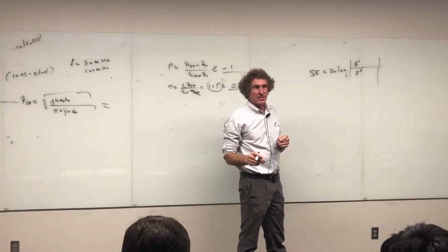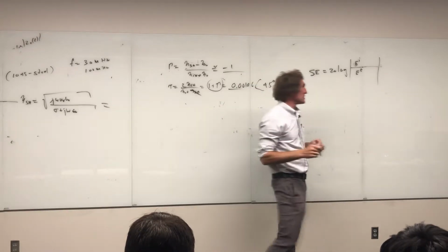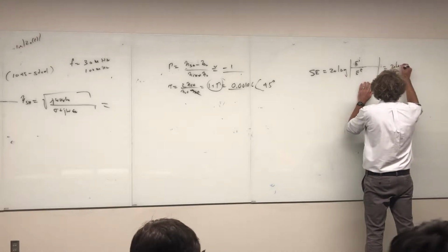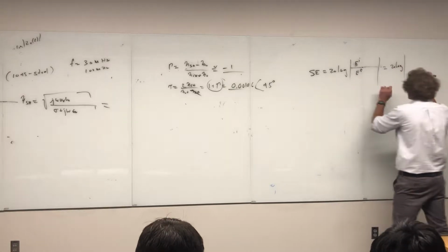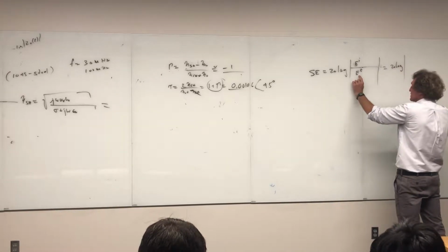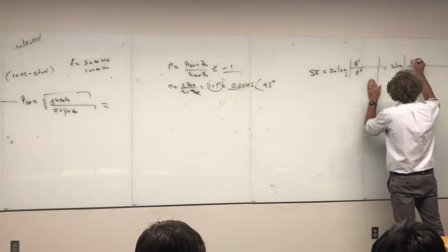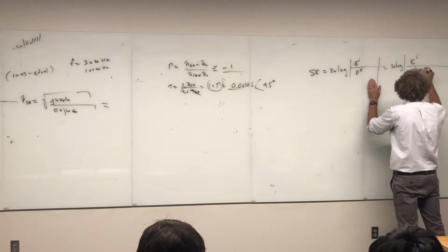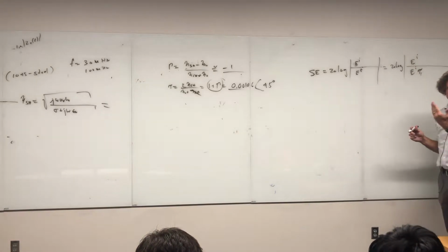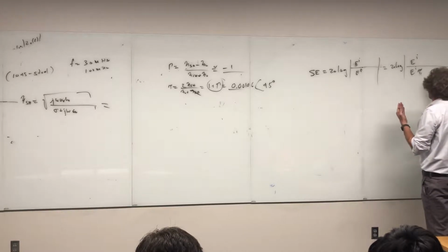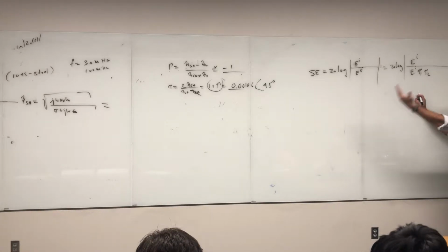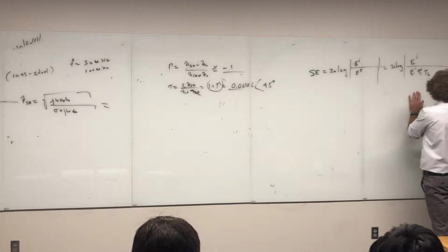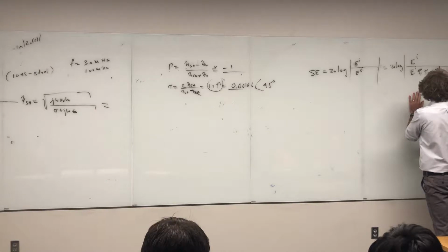It's the ratio of the incident to transmitted field's magnitude. Well, when we look at the transmitted field, I said it was 20 times the log of the magnitude, and the transmitted field will be the incident field. So I'll just put it here so you can see it. There's the incident field, times the transmission coefficient at the first barrier. That's where you hit the shield, right? Then it's times the transmission coefficient of the second barrier when it's coming out of the shield. Do y'all remember this? And then it's times e to the minus alpha d, where d is the thickness.